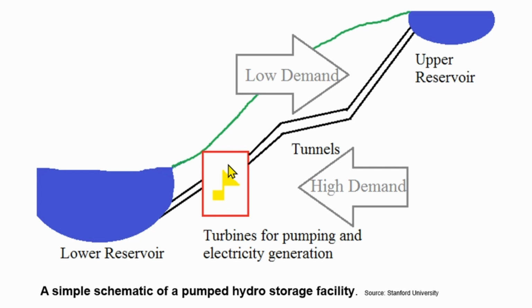This price difference is a bit of a problem in Germany. If you want to use 100% renewable energy, and that's in Germany basically solar and wind power, we have to have storage and compensation mechanisms to balance out the power availability during day and night and during periods of high wind and low wind. These devices are very useful, but at the moment, due to the low flexibility of existing conventional power plants, electricity prices are really, really low, sometimes even negative, because the conventional power plants, for example lignite power plants, can't react fast enough.